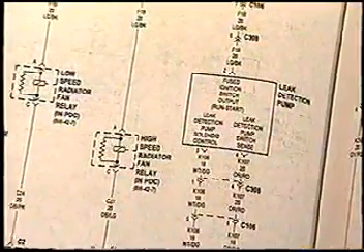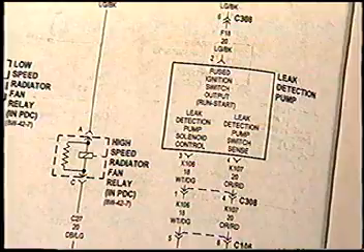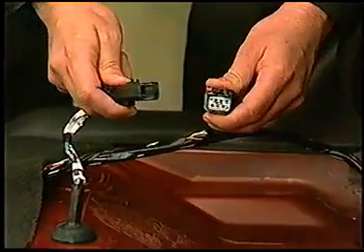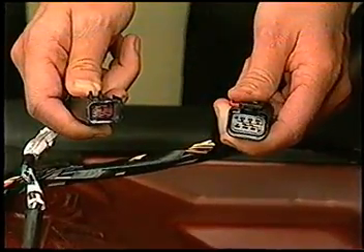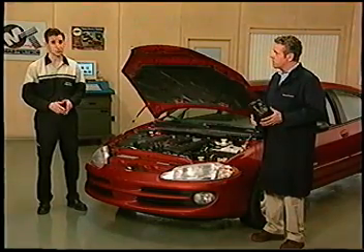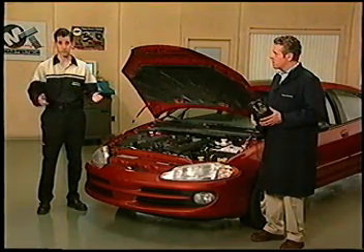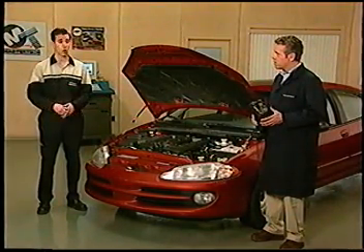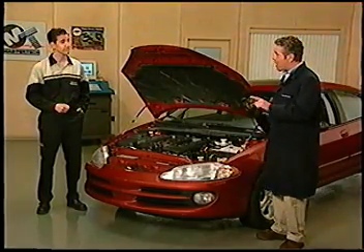By following the LDP wiring schematic in the service procedures, I was able to find the source of the fault, which turned out to be a corroded connector. If I had just replaced the leak detection pump without further diagnosis, I would have made the wrong repair. That's right. And in fact, that fault code is the subject of a TSB.